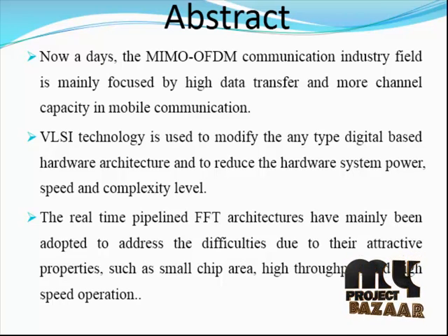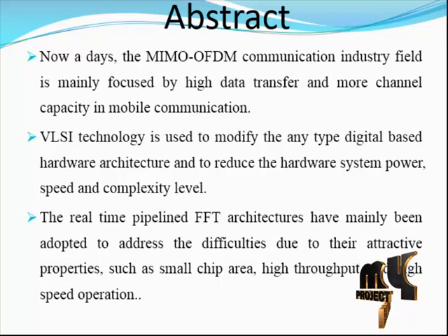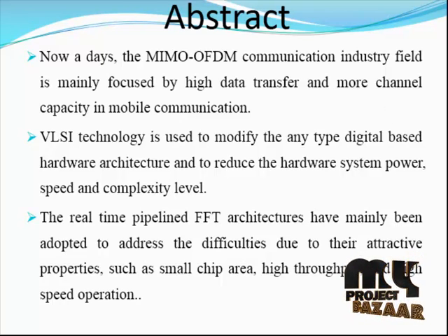Two types of pipeline FFT architectures can be found: single path delay feedback and delay commutator. Further, according to the number of input data stream paths, they can be classified into multipath or single path architectures. The four kinds of pipeline FFT architectures are often adopted when the throughput requirement is beyond the theoretical limitation, but the single path architecture can offer, at a given clock frequency, concurrent read operations for the multipath input data. Therefore, single path architecture.